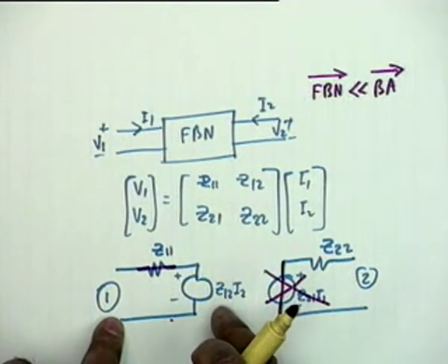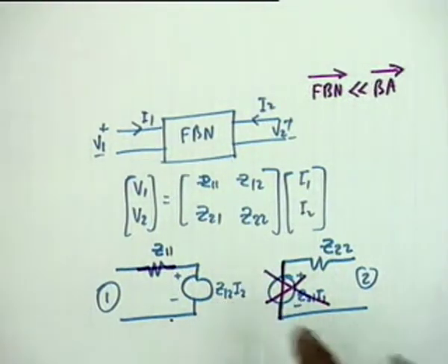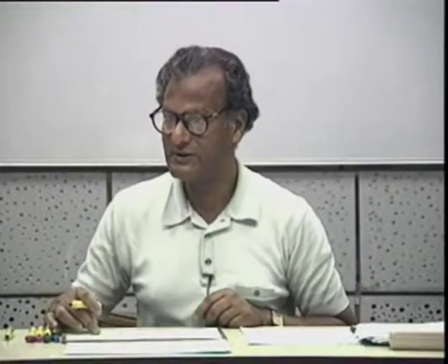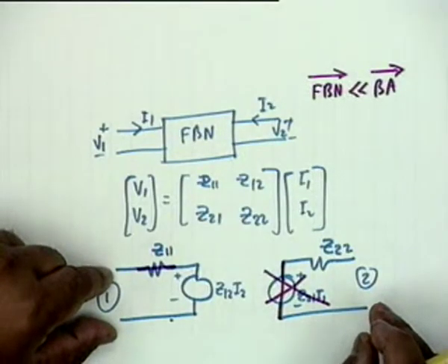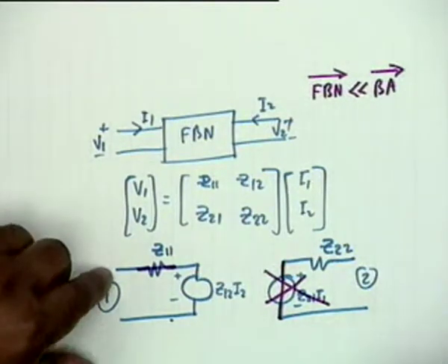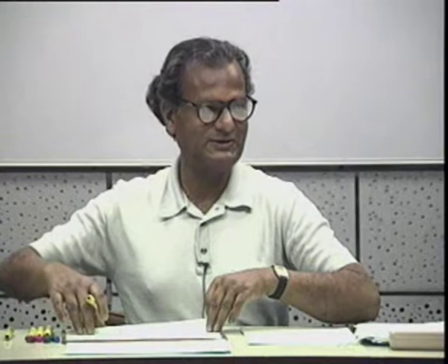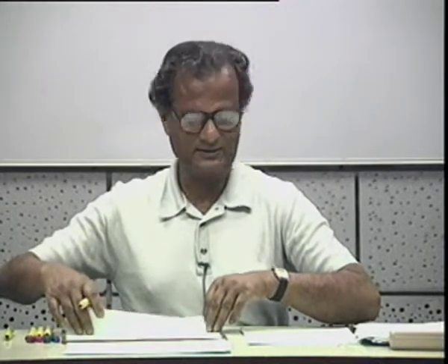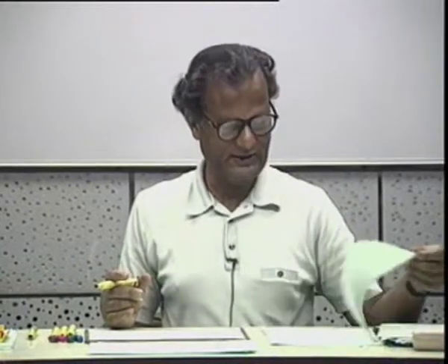Okay, to be able to measure Z12, or beta, Z12 is now equal to beta. To be able to measure it, what you have to do is apply a current source here and measure the voltage under open circuit conditions, and that gives you Z12. This is the total justification. In the other two, I will not make this justification. I will simply draw the A circuit and the beta circuit. But before that, let me take an example.